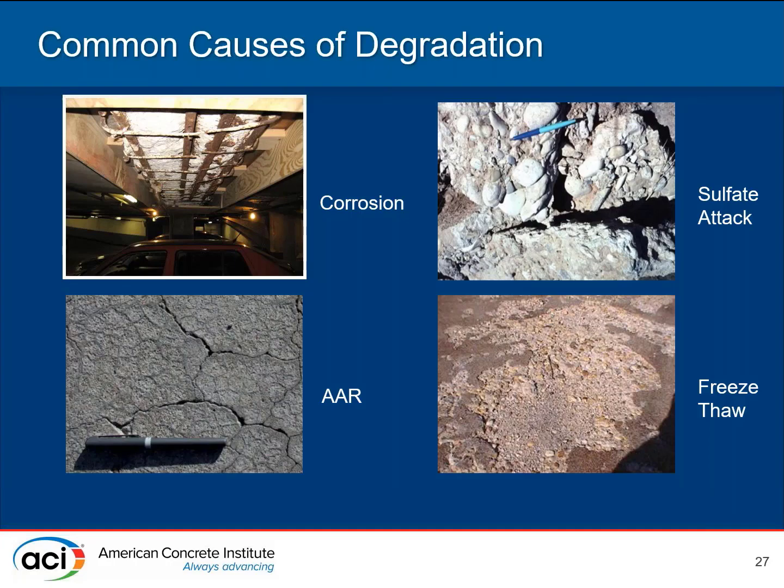Sulfate attack, often from the wrong type of soil. Alkali aggregate reaction: bad aggregate, the wrong type of aggregate, and not being mitigated. Freeze thaw damage, and I like to mention freeze thaw damage because it's not one that typically, I'm not going to say never, but typically leads to structural distress. Very, very rare you're going to have a building fall down because it's undergoing freeze thaw, but it definitely will have an aesthetic impact and a usability impact.